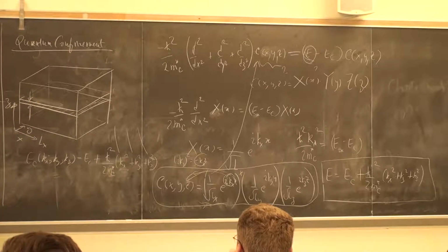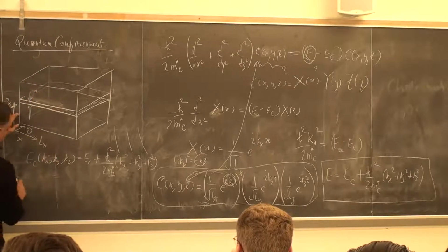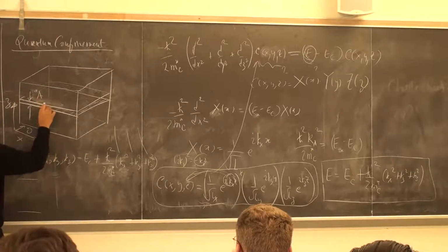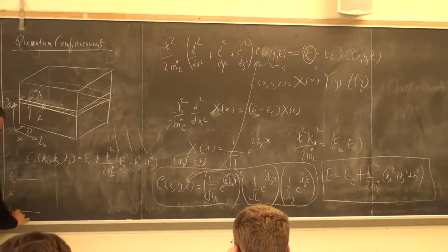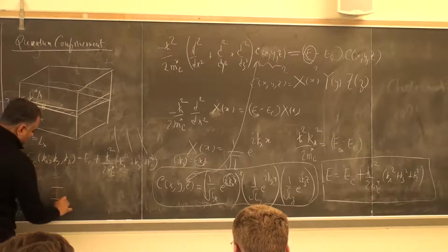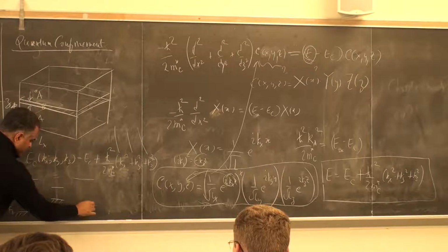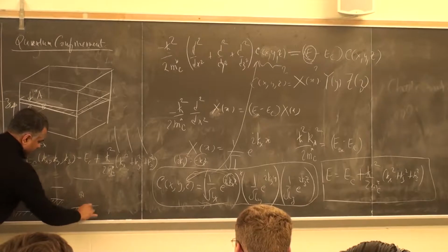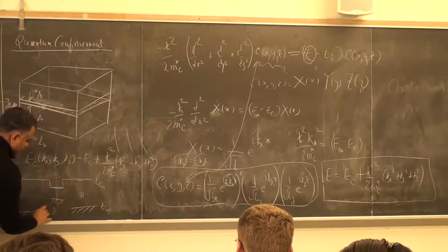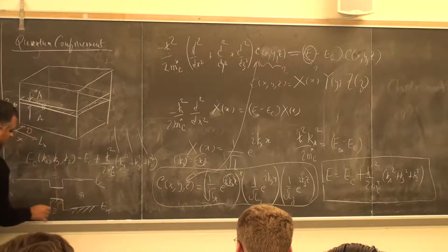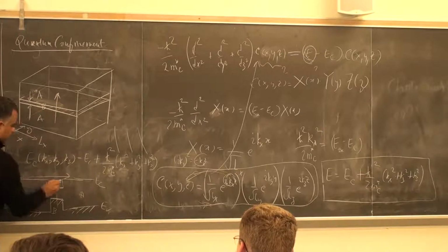in this crystal. This region has a band gap that is, say, large, so A, B, and A. So A has a conduction band edge like here, the valence band is over here, but B has a smaller band gap, something like that. So that's A, that's B, and you go back to A again, EV and EC. So now your conduction band profile looks something like this, and the valence band looks something like that. Does that make sense?